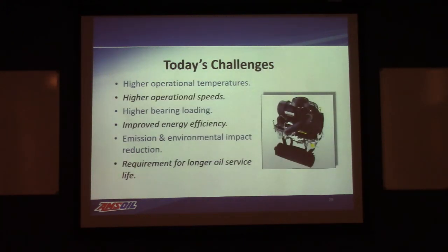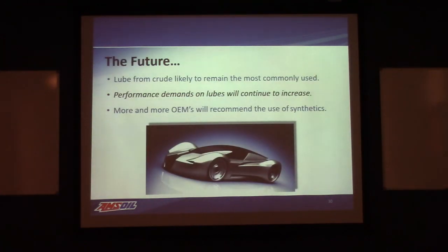Today's challenges, we've already talked about them: higher operating temperatures, higher operating speeds, higher bearing loads. We're looking for improved energy efficiency, going to lighter weight oils, that type of thing. Emissions have placed a lot of additional strain on the engine oils themselves, and even after all these problems, we're saying we want that oil to remain in service longer. You know, it's like, how much can you beat me up? But that's what's being required, and the only real way to go with that is utilizing base materials that can perform at a higher level.